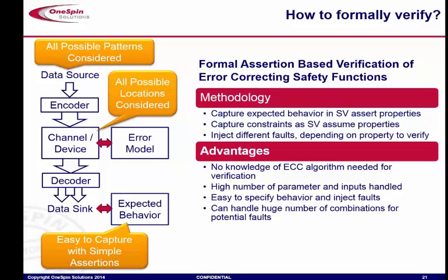And then you say, okay, if I only have an error on 2 bits, can it happen that the error is not detected? And formal does what formal does best. It is looking for the inputs for you. So inputs in the traditional sense, the inputs of the design that produce something, and also the errors to be injected to produce something.